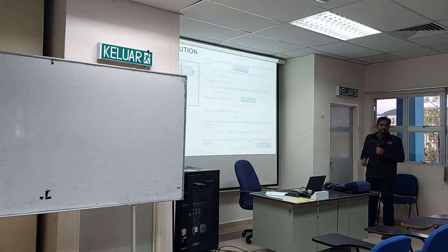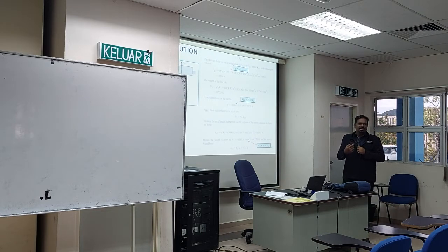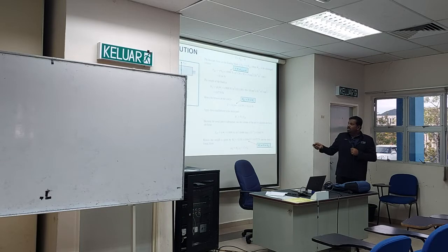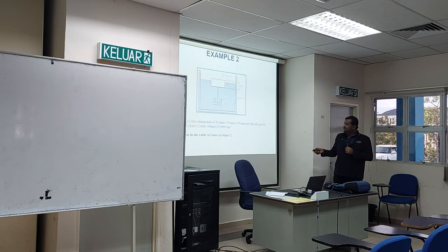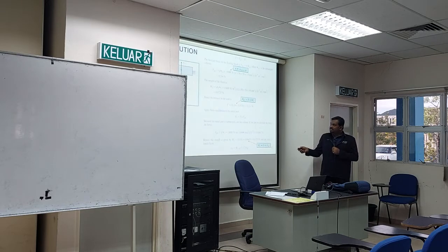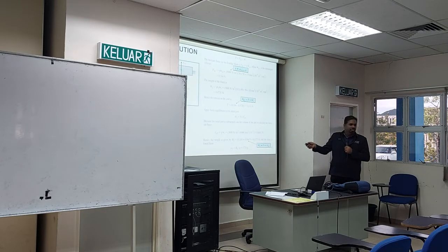Okay, so based on the same principle, when you first get the question, convert it to a free body diagram, then you can see. Like in the picture, you can't see because you don't know what forces are acting. So when you draw like this, you divide it into two. So there are two parts. The first part has buoyancy force acting from below, the direction is upward, and downward are the tension and also the weight.